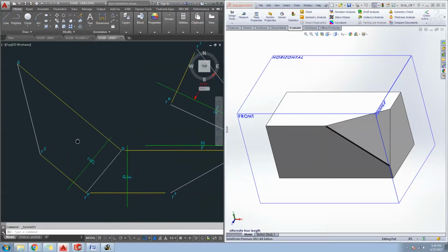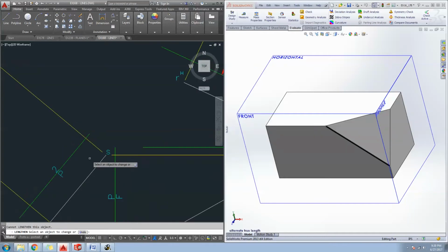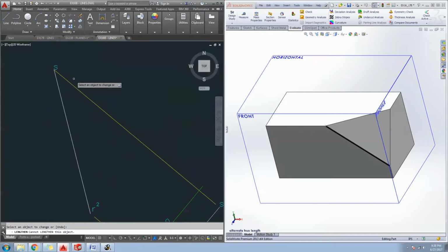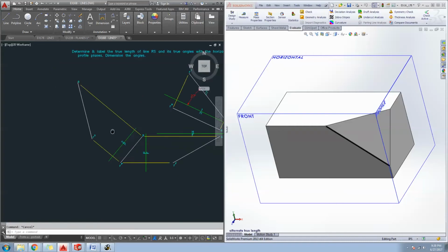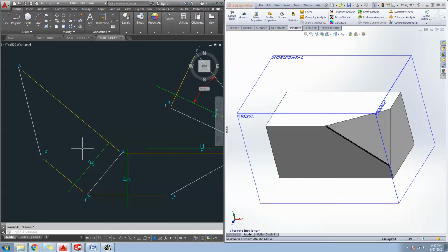as point 2. Type len for length, dy for dynamic, and we will just shorten those projection lines up just a little bit. Now, the whole reason we were doing this was so that we could get the true length of this line, which means that we need to note that this guy's true length. So we're going to take that, copy that, bring it down towards the middle, just that, true length, and then rotate it so that it matches this guy to that guy there.